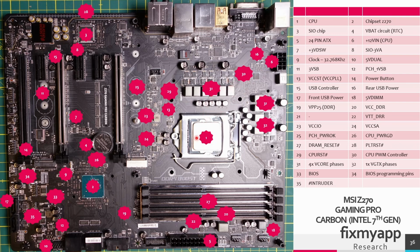The CPU uses the SVID data lines to inform the PWM controller about the specific voltage it needs. This is needed because the voltage requirements are different based on the CPU workload and power state, like idle, boost or high load scenarios. Based on the current state, it will inform the PWM controller what kind of voltage it needs.